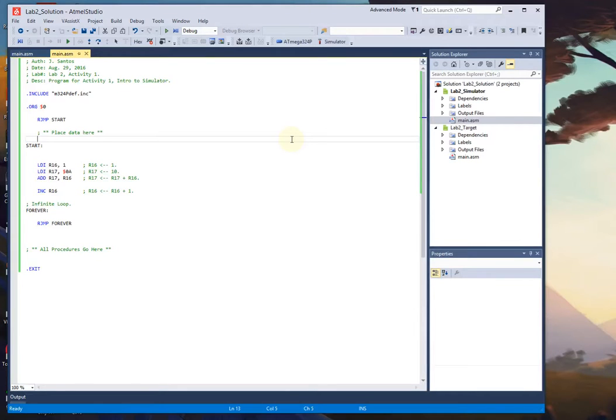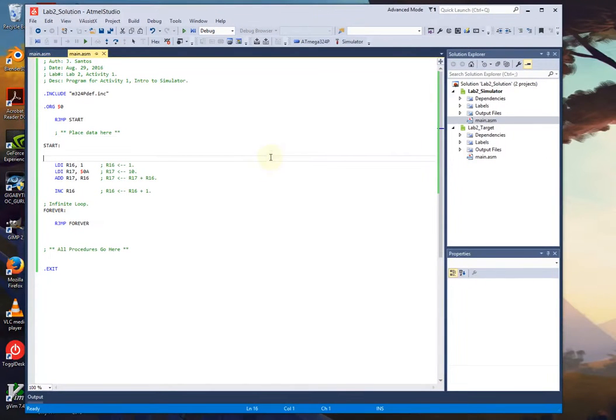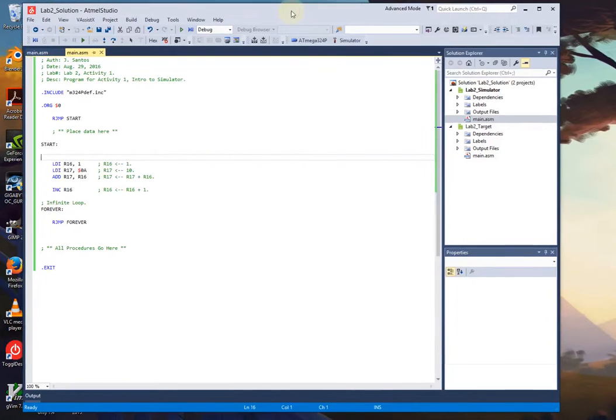All right. Now, we're going to do one more thing here. It's going to be tedious to redo all of these for each new project, for each new solution. Luckily, Atmel Studio, as is Visual Studio, allows you to export a project template. A project template is a ready-made project that contains all the settings in place, so that you can just say new project, and boom, you can go ahead and get started. Let me show you what I mean by that.